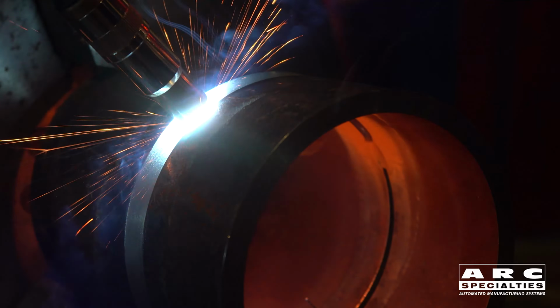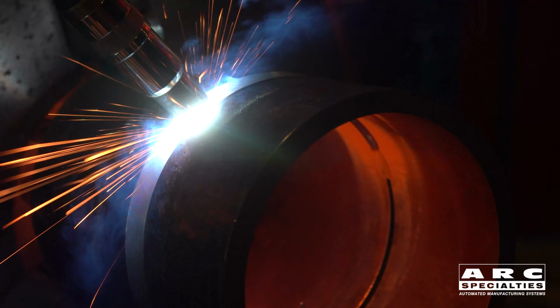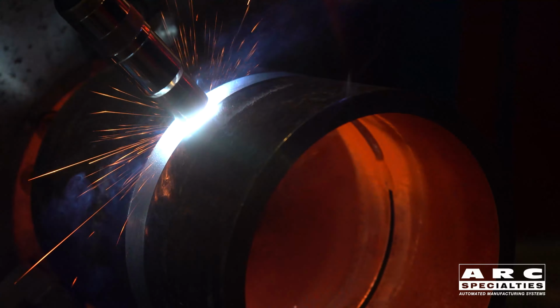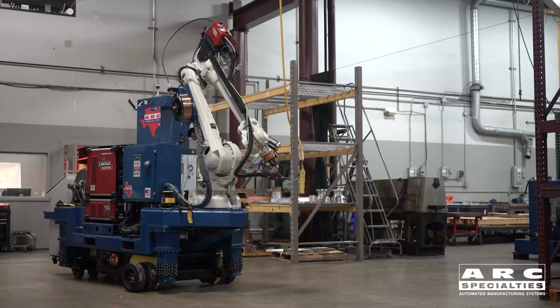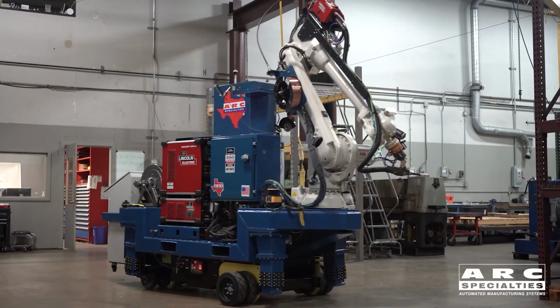However, it's one of the very few welding processes which are not pre-qualified by the American Welding Society for structural welds. The reason for that is it's a very low penetration process, which makes it prone to lack of fusion defects. But short-circuiting transfer is still one of the most common ways people use gas metal arc welding and has many applications in the world.